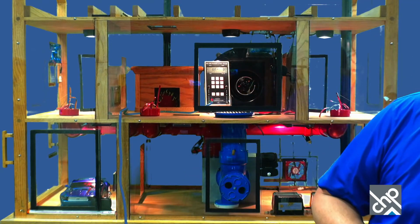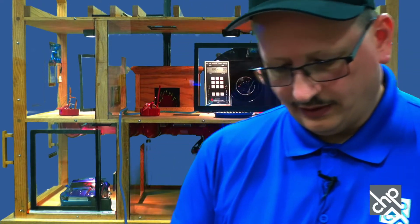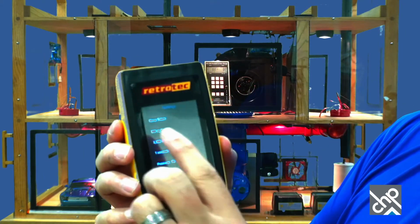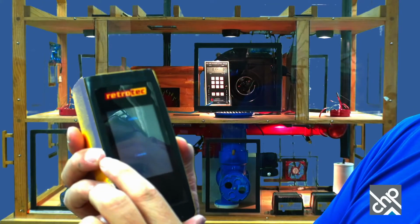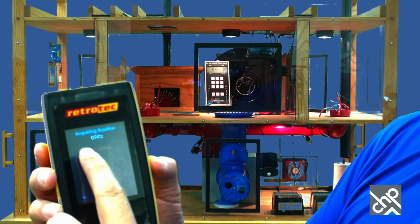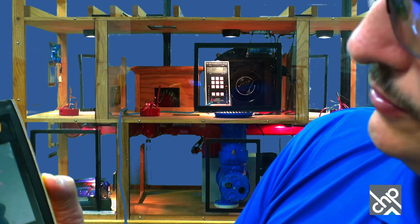One important thing also is, anytime you're measuring pressure to the outside on your manometer, you want to do a baseline setting. For instance, on the DM32 gauge here, you go to settings, then go to the baseline, and then you set capture baseline, and you can see there it tells you how long it's been counting. When you're done with that, you just say end capture. Typically you wait about 30 seconds or so. You just really want it to get steady. And then you hit end capture, and now it's stored in there.